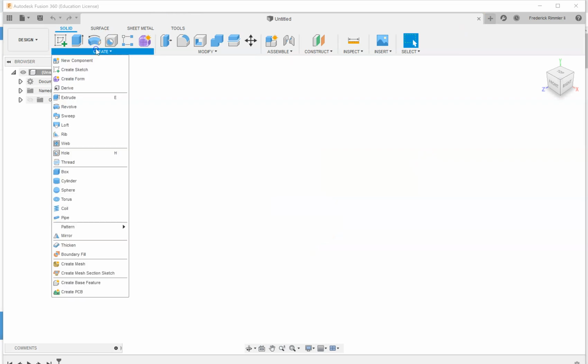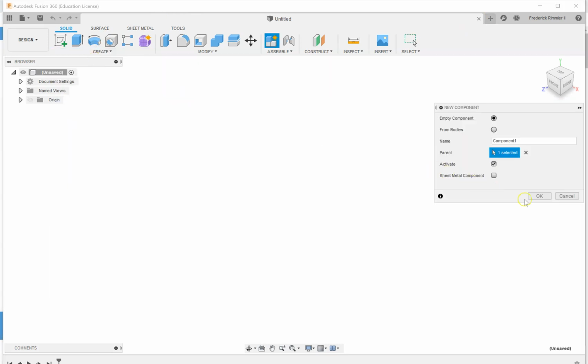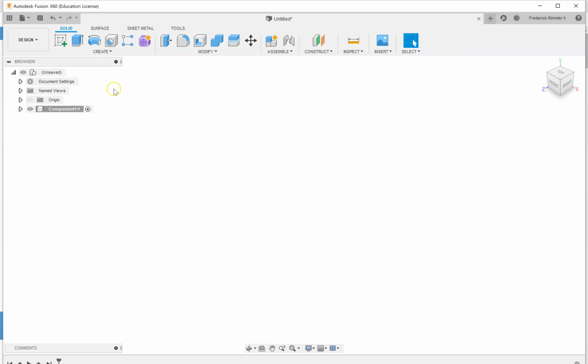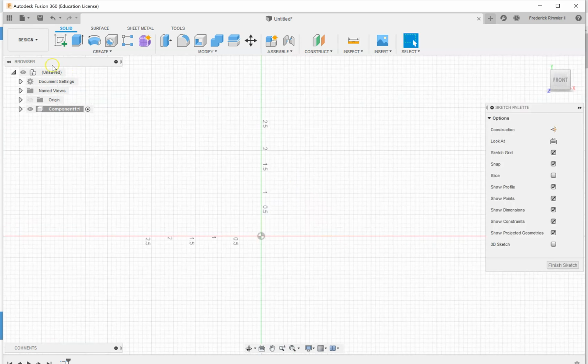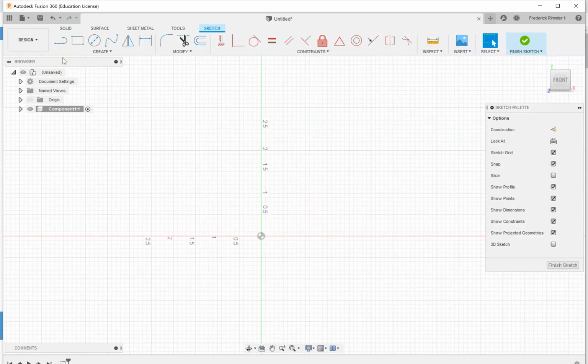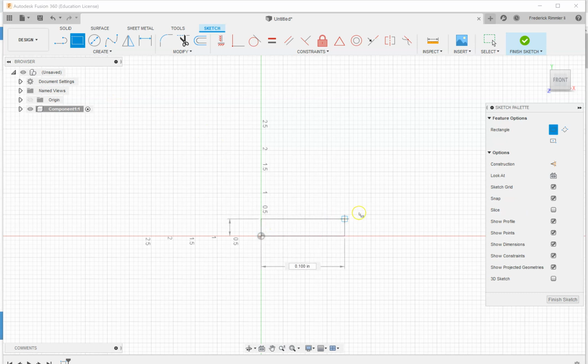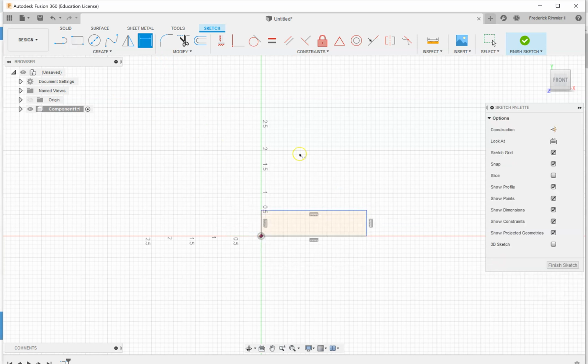Finally, we'll create one more piece. This is going to be our white piece. So I'm going to start with new component, then create new sketch. And so for this one, if I stand it up how we looked at it for sketching, there's a couple different ways we can start off by building this. I'm going to build it from the front back. So I'm going to start with just a nice rectangle that is 0.75 inches tall and 1.5 inches wide.